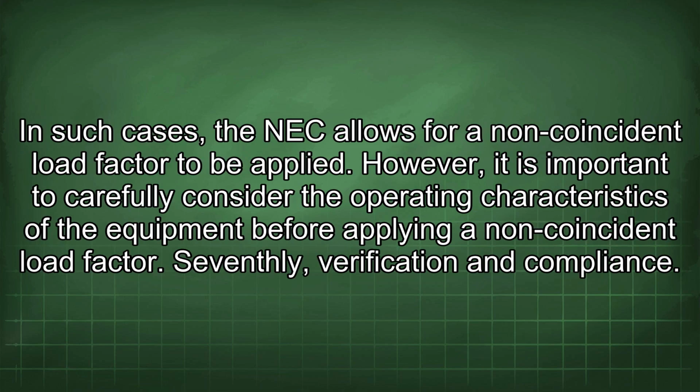In such cases, the NEC allows for a non-coincident load factor to be applied. However, it is important to carefully consider the operating characteristics of the equipment before applying a non-coincident load factor.